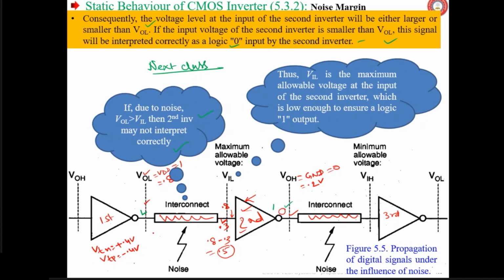So it is going to offer more resistance also. So a resistive drop will be there. Plus nearby another interconnect line will be going. That may carry some signals like clock. That clock signal will be affecting this signal. So it is going to cause a huge problem.